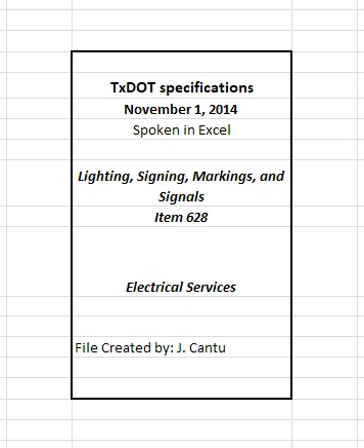3. Construction. Perform work in accordance with the details shown on the plans and the requirements of this item. Use established industry and utility safety practices when installing, relocating, or removing electrical services located near overhead or underground utilities. Consult with the appropriate utility company before beginning work.